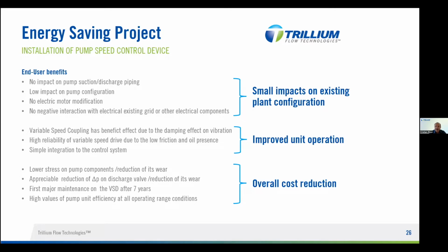In terms of impact on the existing layout, the impact is really small. In fact, the pump does not move, so we do not have to modify suction and discharge piping. In terms of pump configuration, there are just a few impacts that can be handled directly on site. In terms of electric motor, we don't have to modify anything since we can use the same electric motor. Again, we don't have to modify the existing electrical grid either.